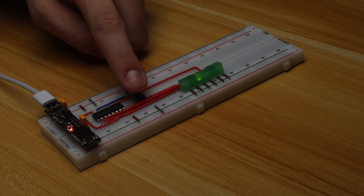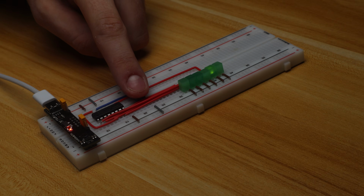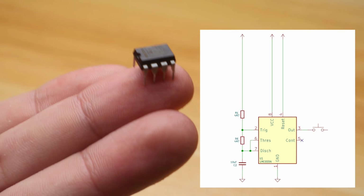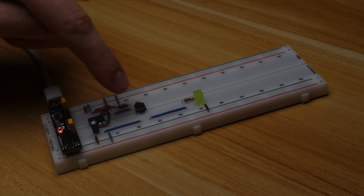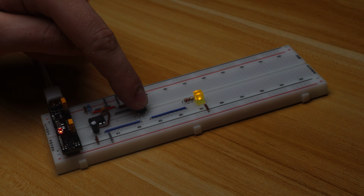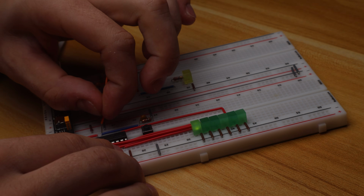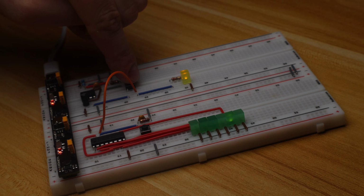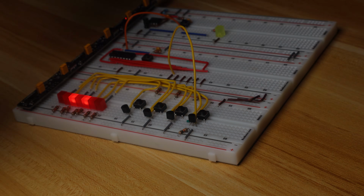The decade counter is a sequential logic device that advances from one state to another on every clock cycle. Instead of using a button to loop through the LEDs, we can introduce a simple 555 square wave generator which will produce a clock signal. We can combine this with our decade counter, and this in turn will also introduce a sense of randomness, since it will be difficult to always make it stop on the same phase. I can combine this with our original 4-block selector.